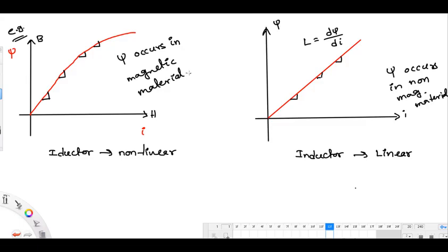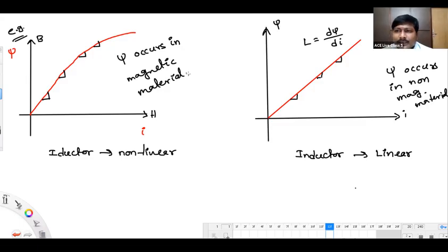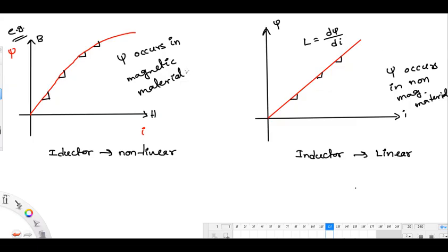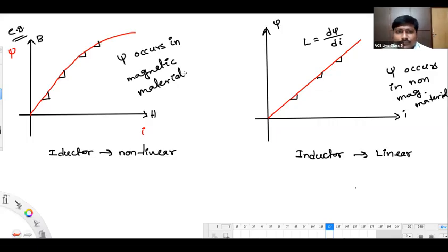We consider the infinite bus as the power system and the generator to be studied, because doing stability analysis on a multi-machine system is laborious for us right now. Yes, sir. On whichever machine you want to do stability analysis, concentrate only on that machine and isolate the rest as an infinite bus. All right, sir. Thank you, sir.